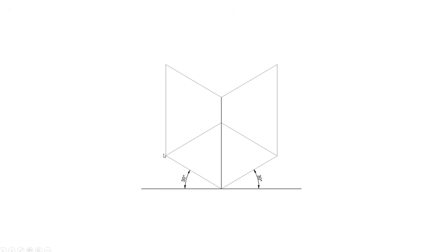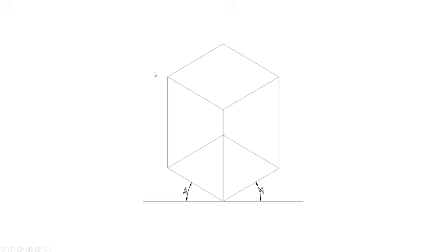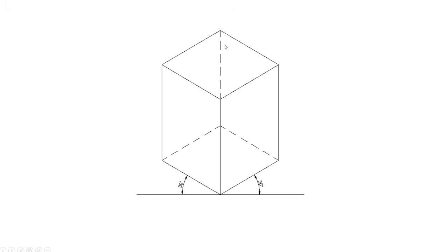Now from here you mark 70 mm upwards, here also 70 mm upwards. Now from here a line parallel to this one, and another line parallel to this line like this, you will get this point. Now in the case of a square prism, this inner point, all the three lines to that point will be invisible because this is the other side, and this is the bottom, a base corner which is coming on the other side, a corner opposite to this corner. So this corner, there three lines are meeting, those three lines will be invisible.